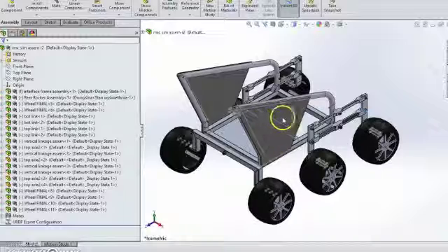The next thing of note is that we repositioned our assembly such that the origin is in a logical place. Now this is important because the origin is going to dictate the moment of inertia of the central chassis or the base link.